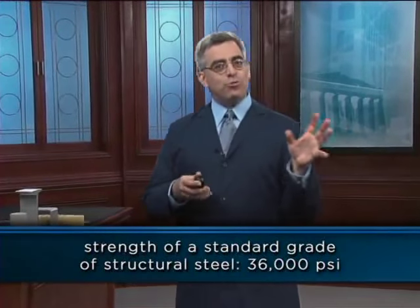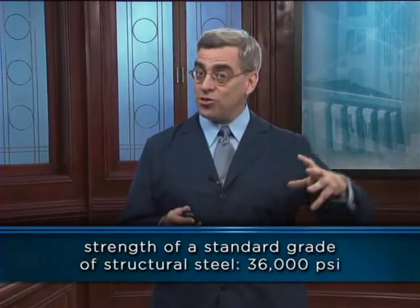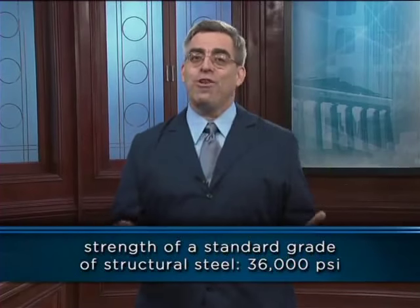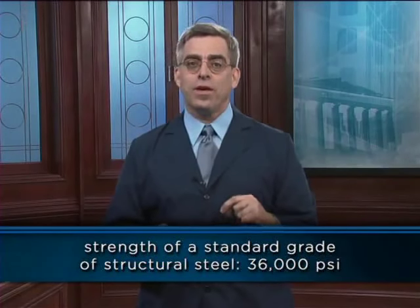The concept of stress is so powerful because the strength of a material is defined in terms of stress. For example, the strength of standard grade structural steel is about 36,000 pounds per square inch. Doesn't matter if the piece of steel is long or short, wide or narrow, circular or eye-shaped, the material will fail when the stress reaches 36,000 psi.